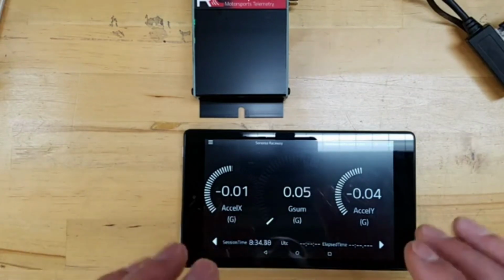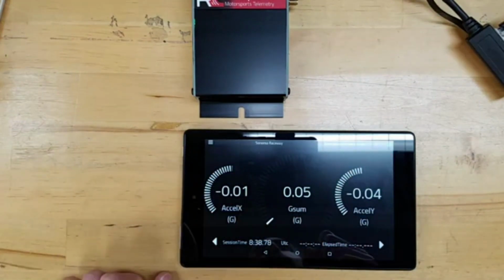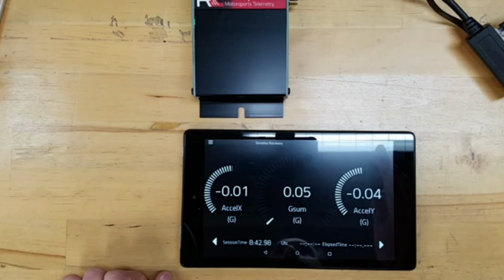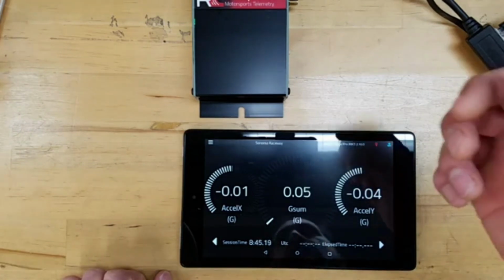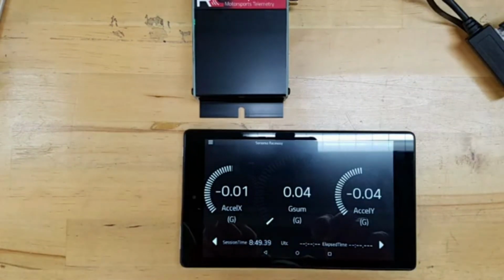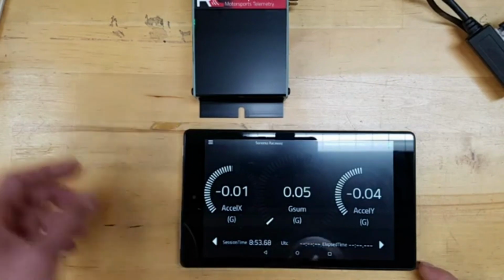left and right. But if it looks more like a D, or kind of like an oblique round shape, that means you're braking and also using your maximum amount of traction while doing threshold braking, cornering, and also accelerating, so that the corners of that T and the scatter plot are filled in. And this GSUM can help visualize that.